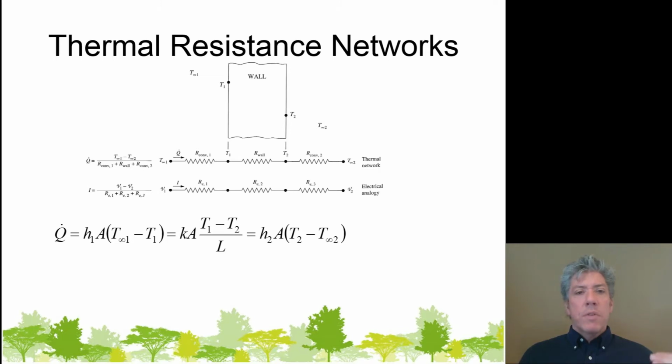That's what drives thermal energy through the air inside of the home to the wall. The next term represents the conduction through the wall and is the same rate as from the air to the wall, and then finally convection in the outdoor air is the final term. And again, these represent each of the resistances and the heat flow rate through each, by analogy, the current through each.